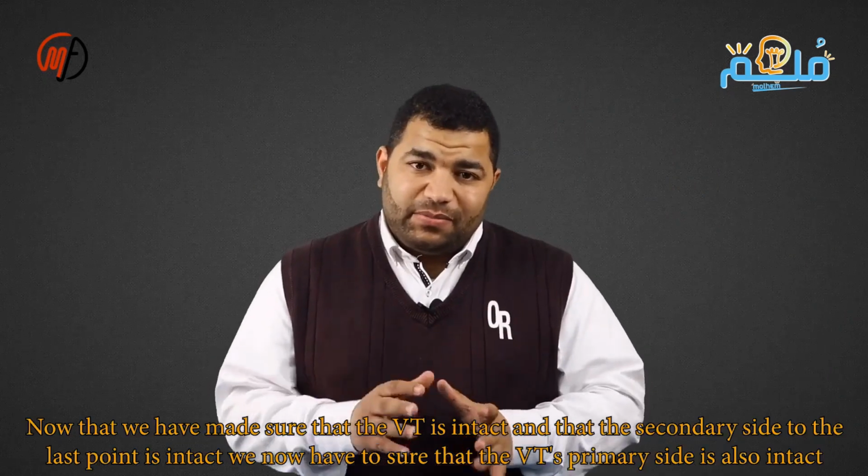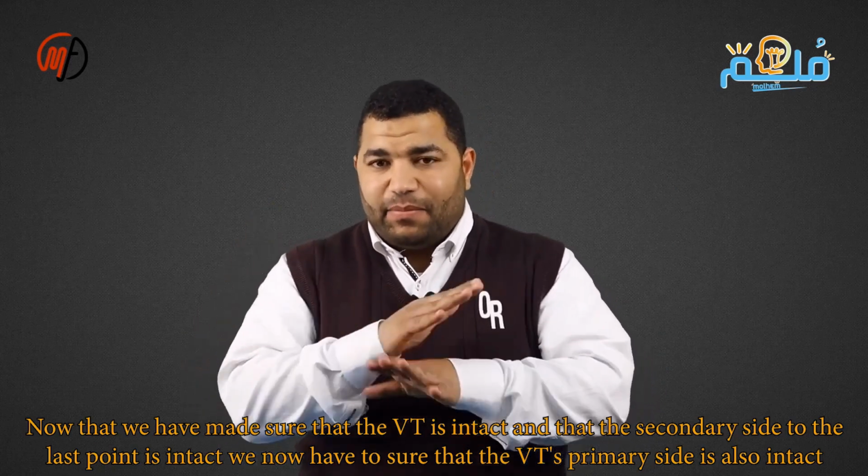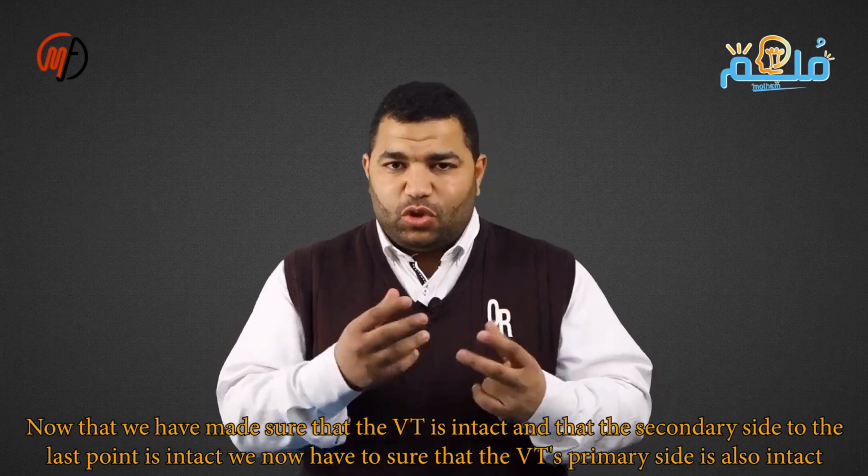Now we have confirmed that the VT is functioning properly and that the secondary side is good all the way to the last point. We just need to make sure that the primary side of the VT is also in good condition.